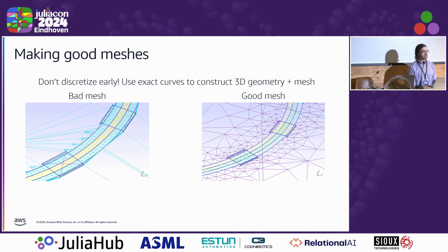So if you do the naive thing, if you're working with a polygon-centric tool, which is very reasonable, since a lot of fabrication tools are going to want polygons to draw the device, then if you have a nice curved wire here, these are circular arcs, but we've discretized them too early. They're now piecewise linear shapes with a ton of points on them, and the mesh wants to connect all of those points, and we end up with a lot of long, skinny triangles, which is bad.